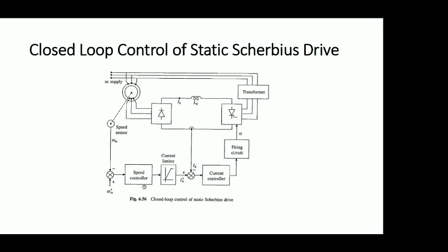So if you want accuracy, then we will be going for PID. If you are going for PD, then there will be an offset. If we are going for PI, then the offset will be 0, and in the PI, the time required to reach the steady state will be greater. All that we have studied in the control system part.